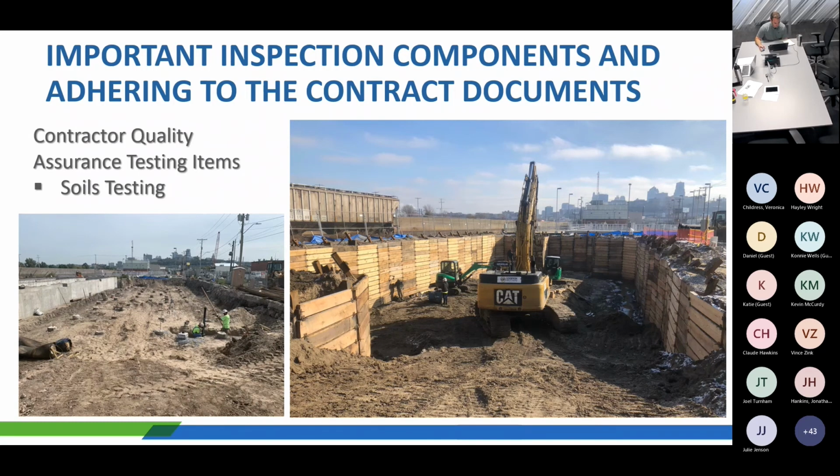Other things are going to have these third-party elements to them, and these third-party companies are going to need notices. They're going to need time to get out on site and set things up, and at times pull together information as well, like soils proctors and things like that. So having them embedded and talking to the contractor and involved with the planning of the project is important from day one, so that they know when these tests are going to be needed.